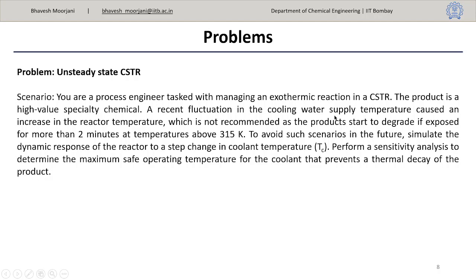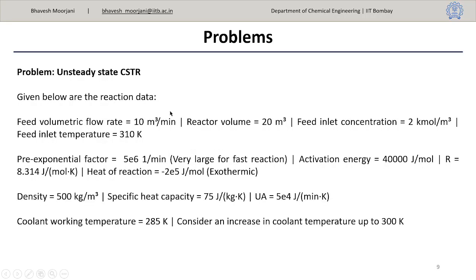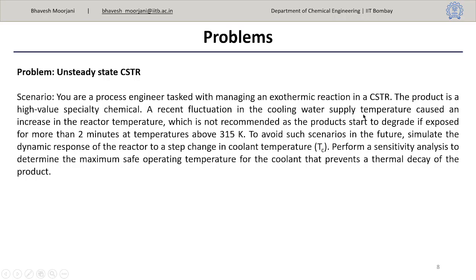The recent fluctuation in the cooling water supply causes an increase in the reactor temperature, which is not recommended, as the product starts to degrade if exposed to more than 2 minutes at temperature above 350 Kelvin.